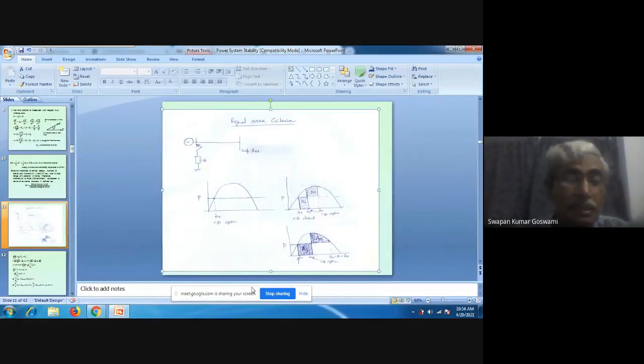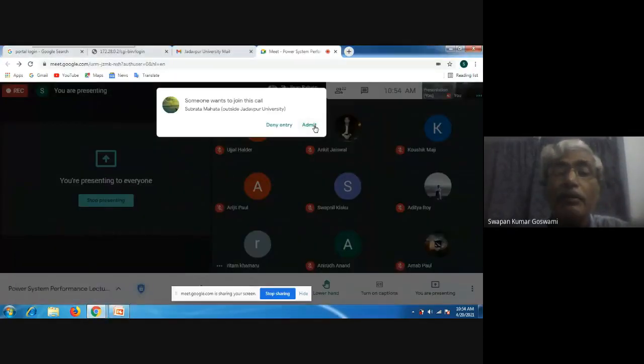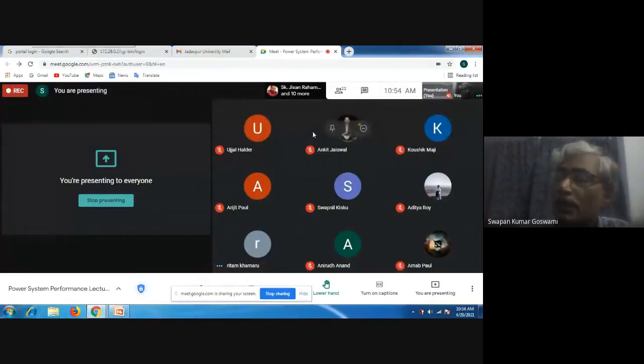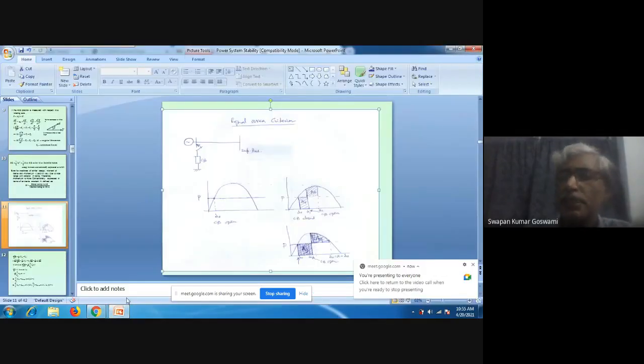In the first swing, the tendency of the generator is to retain synchronism. Why? Because the speed has become above synchronous and then it has decreased, it had become synchronous, and then it has started becoming less than synchronous. So the first swing is completed. So this indication that speed increasing and then decreasing is an indication that the generator will become synchronous. The generator will be restoring the synchronous speed at the new steady state, and we shall be believing in this hypothesis now. Now, if this is the situation, let us investigate this in further detail.